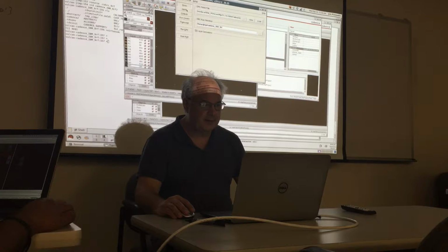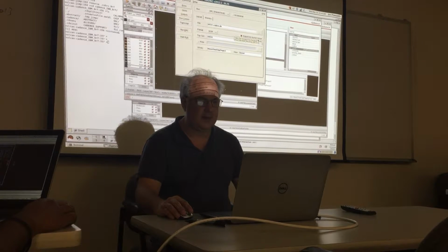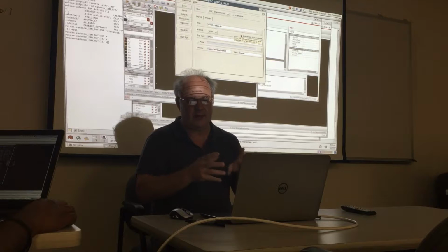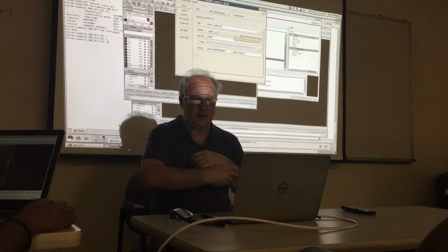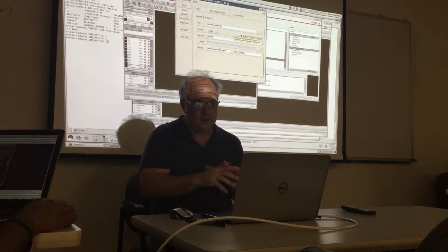So the only other thing that you typically change, I've played with all kinds of things here because when you have different reasons to do things, you have other options, and Calibre's done a real nice job. The only other thing you have to make sure of is that you export from the layout viewer. It's going to create a file that it's then going to use to check against the rules that IBM has set up. And so you got two choices.